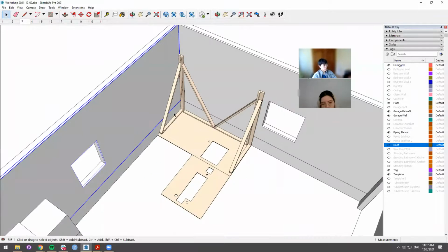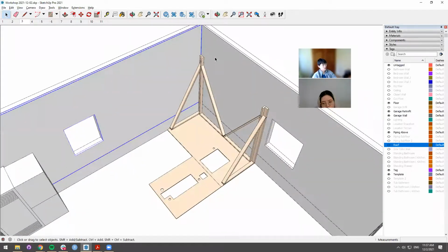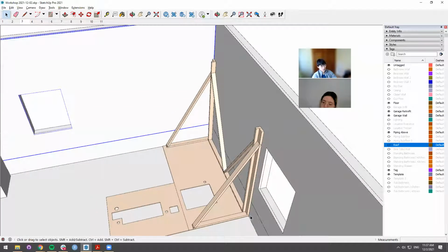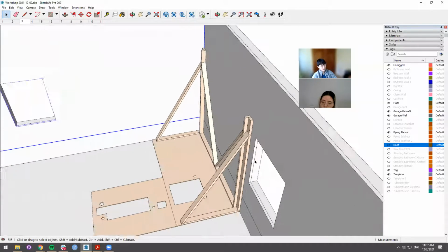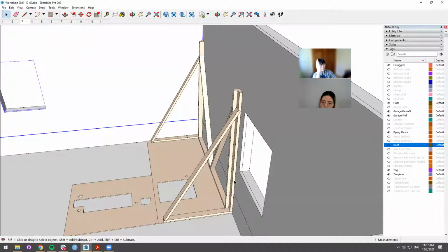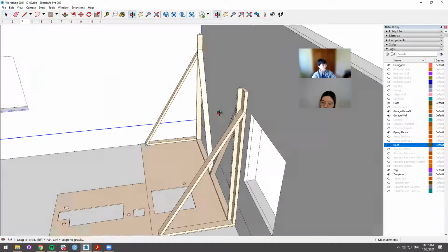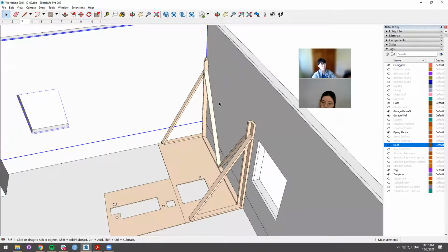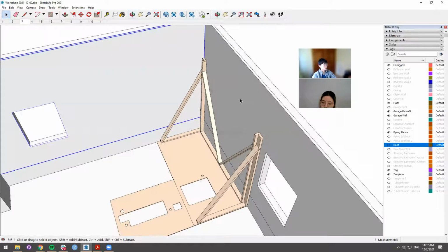You can see here that it's got an overall width to plug into that corner, but it's got these easy stands that can mock up a flat edge to a wall that eventually will be there that needs to hit correctly at the top. And if you put this level up, you'll notice if the existing garage wall is slightly sloped outwards or inwards. And those are important things to correct because that might have to be a structural connection or you'll have to deal with that at some point. So we figured that this is part of that furring step to make sure that you actually have the appropriate connection point with surfaces on the walls, on the 2 walls you'll use.